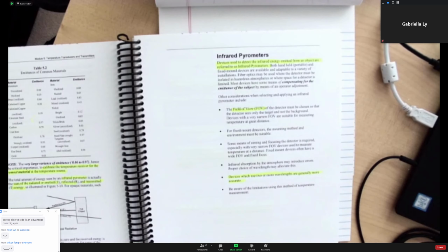It's also very usual nowadays for maintenance people to have thermal imaging cameras. Even electricians want to check the panel and the equipment, because usually the big cable connections are where, after certain years of wear and tear, and in year one you learned about copper conductors and aluminum conductors, over time the metal tends to loosen in the connection by itself.